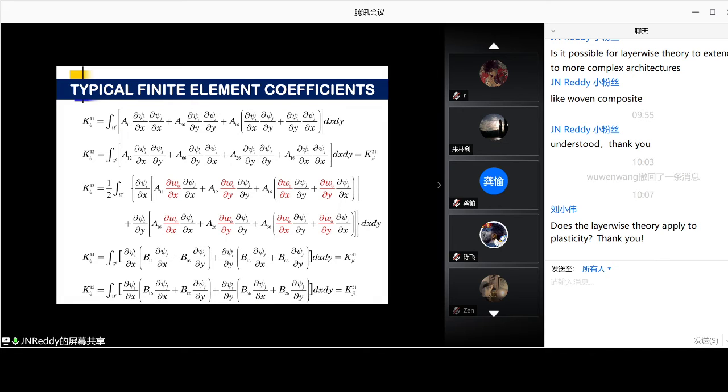At the very beginning of the iteration, we assume the solution to be 0, so that the nonlinear terms drop out. So the first iteration solution is the linear solution, which is also a good thing. This is the nice thing about structural mechanics, because it always has a linear part, then nonlinear parts. When the nonlinear part is 0 at the beginning of the iteration process, you get a linear solution.